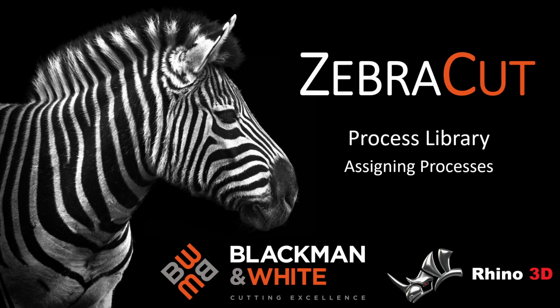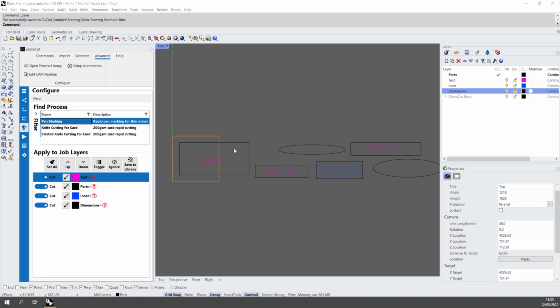In this video, we're going to explore how to assign processes to different geometry within ZebraCut. So here's our job. Our job is on a number of different layers in Rhino. So you can see I have a text layer with some text which I would like to pen mark. I have some inner shapes which I need to cut. And obviously I have a layer called parts, which is all of the outer contours of my shapes.